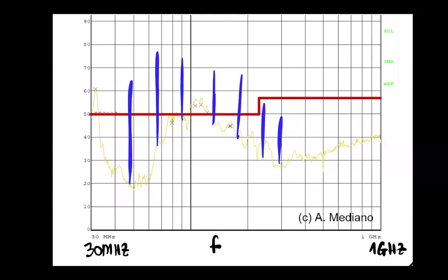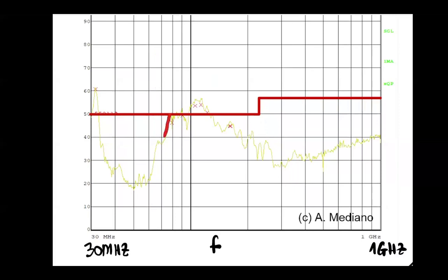But the problem we will be analyzing today is when we obtain something like this mountain. You can see here that at some specific frequency range, close to FM radio, this is 100 megahertz, exactly here, we are over the limits some decibels. Remember from my previous seminar, day number 1, we were talking about trying to go with the emissions below the limits at least 6 decibels, to have some kind of margin. If you are close to the limit or you are 1 dB below the limit, this can be dangerous.